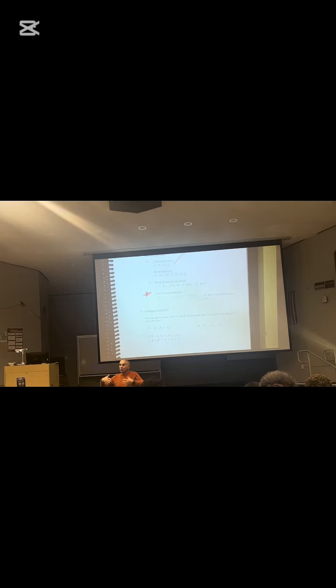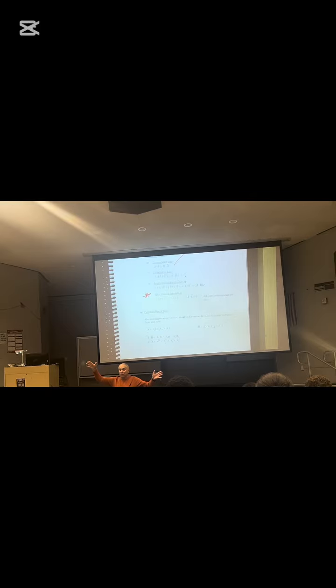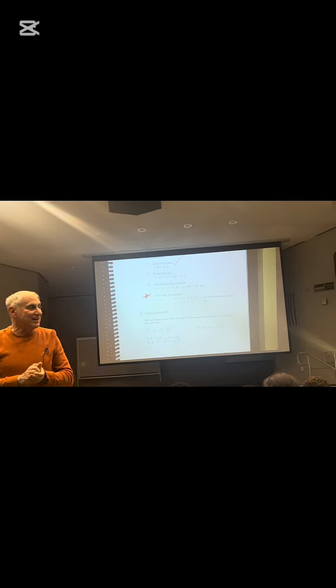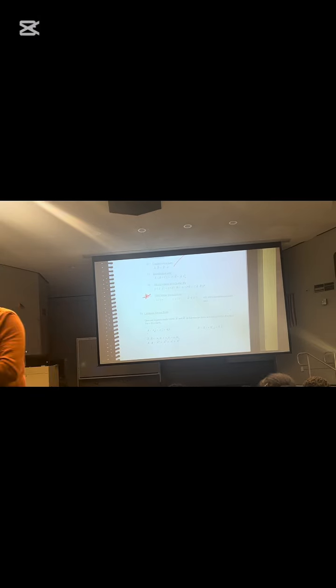But what if I give it to you in 3D and I don't tell you to find it on the X, but find it on some arbitrary line. So find me the component of this force on line AB. Arbitrary. How do I do it? According to number 2 on page 44, it says, hey, find the unit vector of the line AB. Dot it with the vector that you're trying to project. Wow, that's pretty powerful. Right?